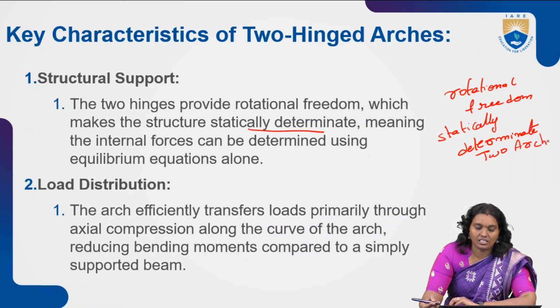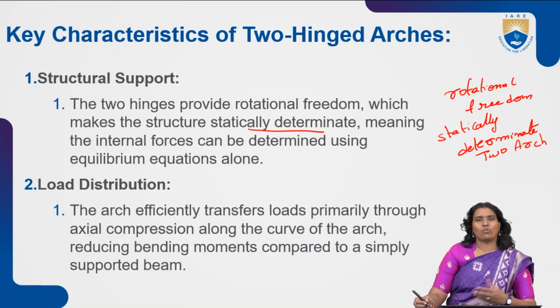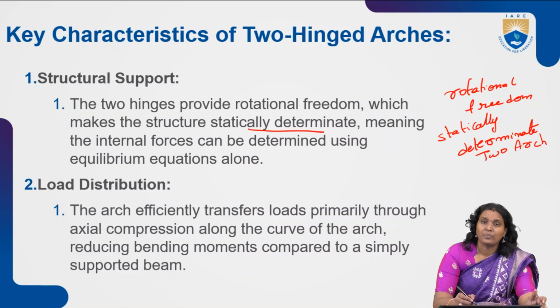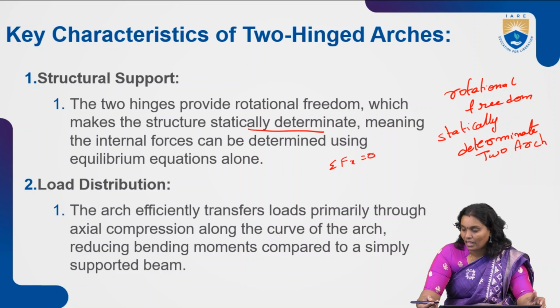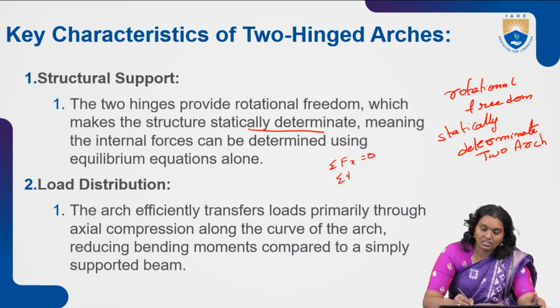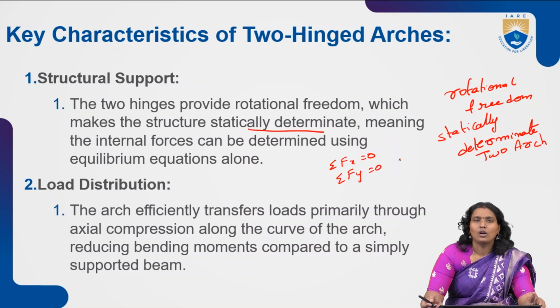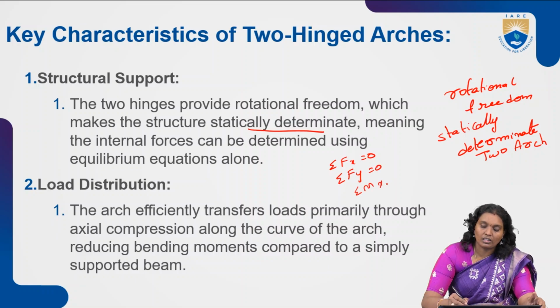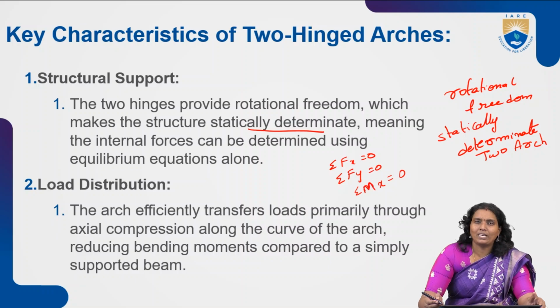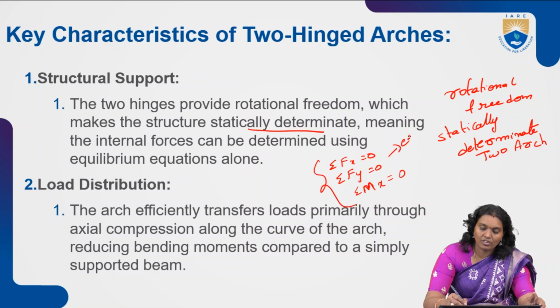Based on the equilibrium equations, what are the equilibrium equations? Those are along the x-axis, the sum of the horizontal forces should be 0, and the sum of the vertical forces is equal to 0, and also the moments according to the loads. The sum of the moments should be equal to 0. These are the statically equilibrium conditions.